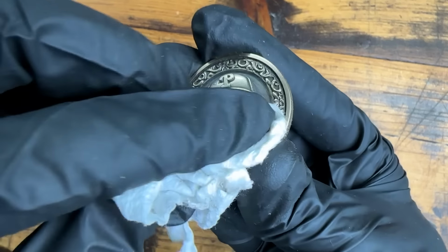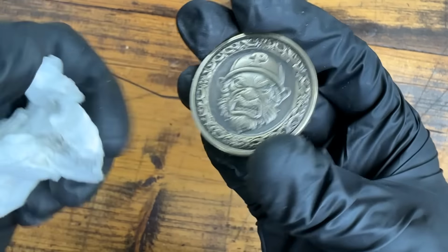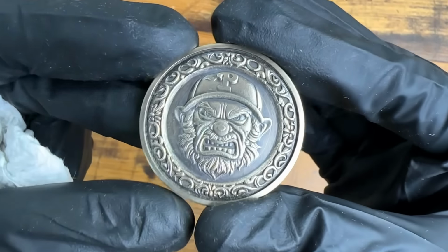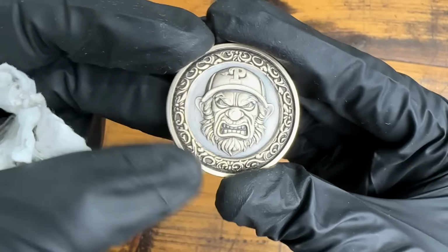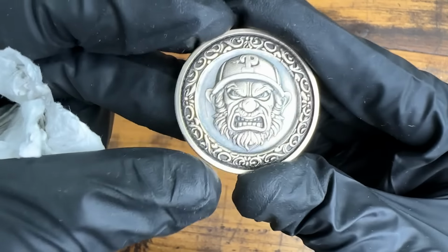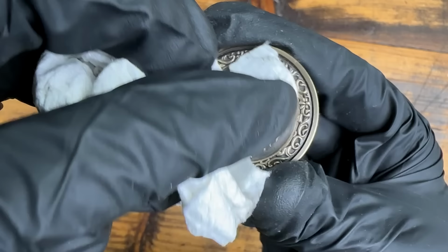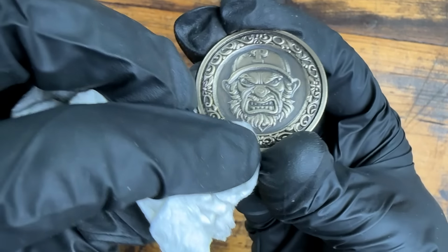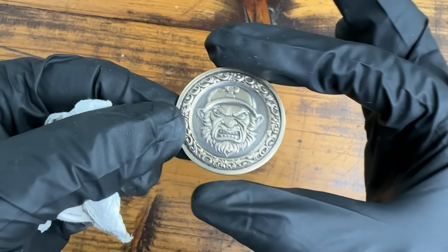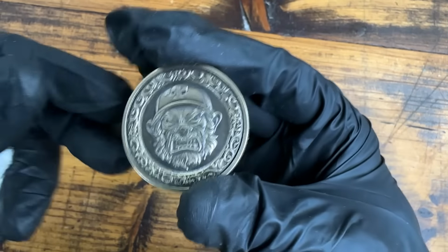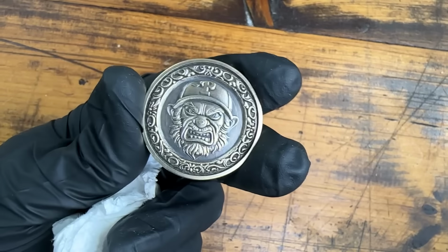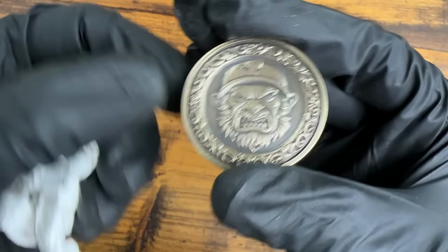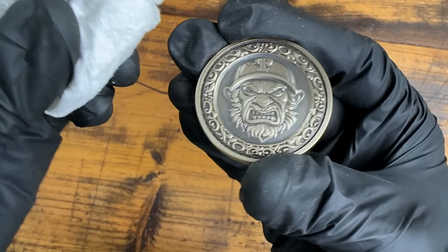And here's a finished look at that final attempt where I changed my frequency to 100 kilohertz and I applied some brass black, but this is definitely the frequency for me. The background is nice and smooth. There's nice details throughout the face. I have to fix the file a little bit just to get some of these errors out of here, but overall, this coin really looks nice. And honestly, I probably wouldn't have even tried it if it wasn't for the experiment that we ran today, where that 200 came out looking pretty good. So I figured I could probably bump this up a little bit into the 100 range. And I think that's where I'm going to stay.